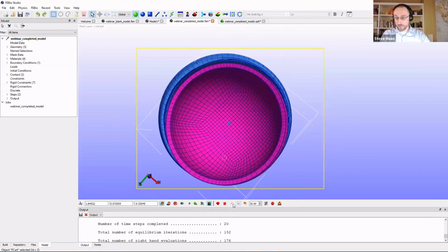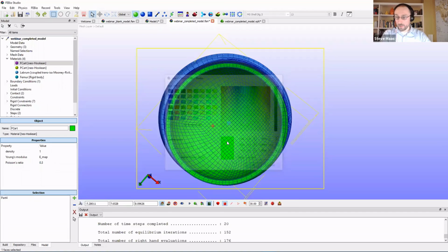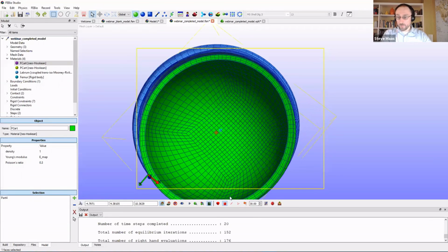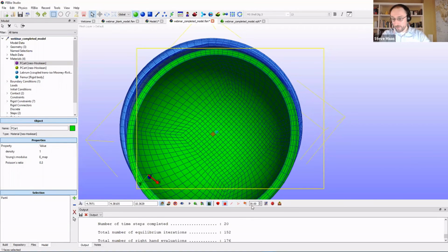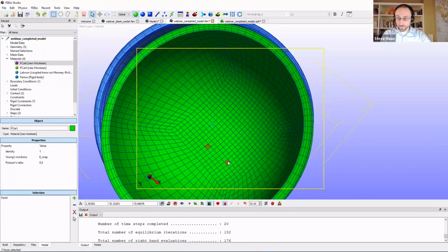Once I have the mesh selected, I have these tools available to select individual items. So let me change the color here. That purple is not helping. So there's a couple different options here that affect what will be selected. If I don't have any of these options on, and I click on a facet, it'll just select that facet. If I shift click, I can grow my selection. I can add, so it'll keep everything I have selected.